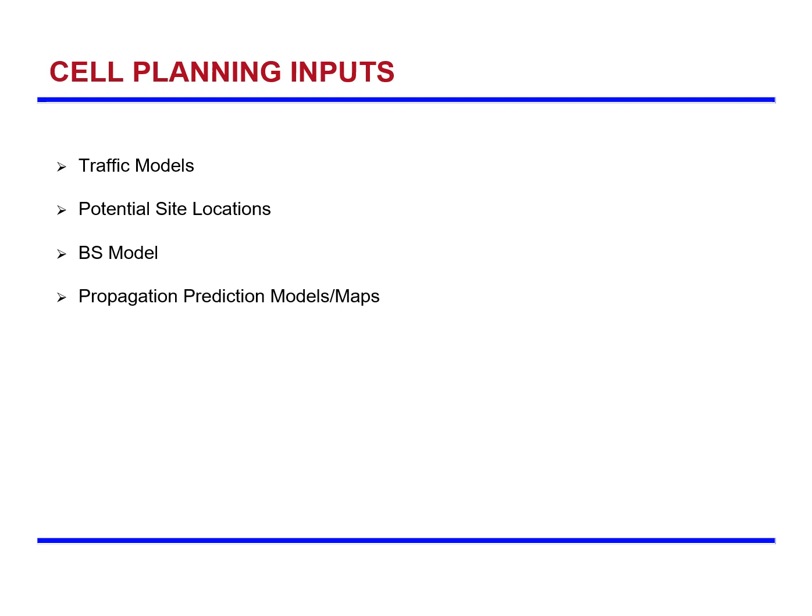Very sophisticated planning tools rely on actual measurement based propagation maps or ray tracing based complex analysis to predict the propagation. However, obtaining complete propagation maps of a large area using these methods is a very cumbersome, time consuming and expensive process. For this reason, different empirical models have been proposed in the literature.